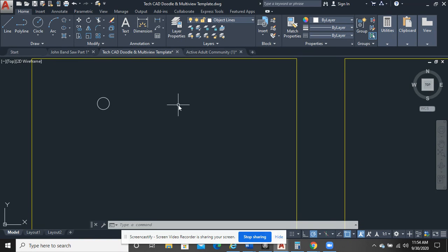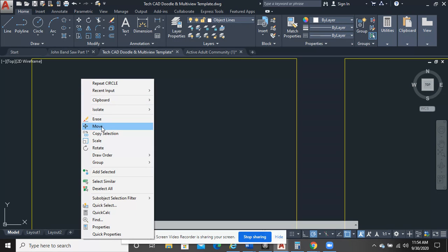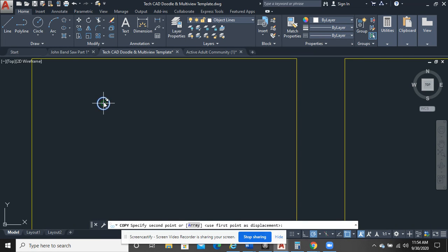Now, let's say I wanted to have a whole grouping of half-inch circles, okay? So I could go ahead and copy this, and I could just go over here. Let's say I want 2 inches of space between them. So I can type that in. I just typed in 2. I kept going in the same direction. I typed in 4. I'm going to type in 6, right? I can come down here and type in 2. And now I kind of get to the end of the road.